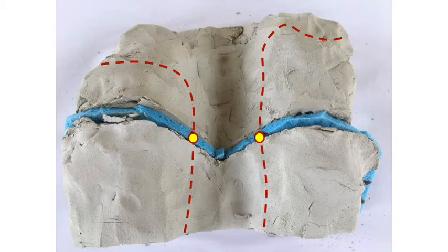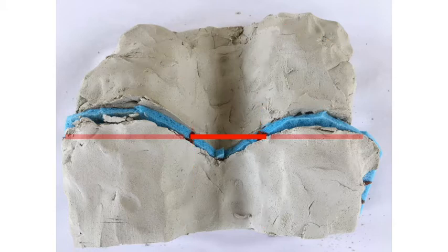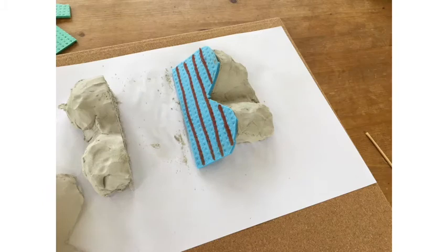And if we join those up, we're connecting points of equal elevation, not only in the landscape, but also on the geological surface at the top of the blue sponge. And this contour of equal elevation on the top of the blue sponge continues beneath the clay, as shown there. So this is a structure contour, and if that was a pick at 100 meters, because that was the elevation of the topographic contour, that's a structure contour on the top of the blue sponge at an elevation of 100 meters.